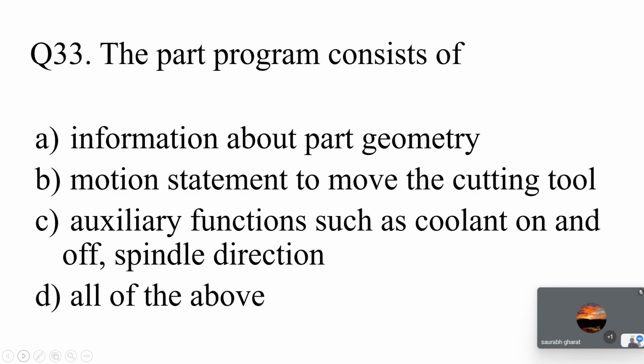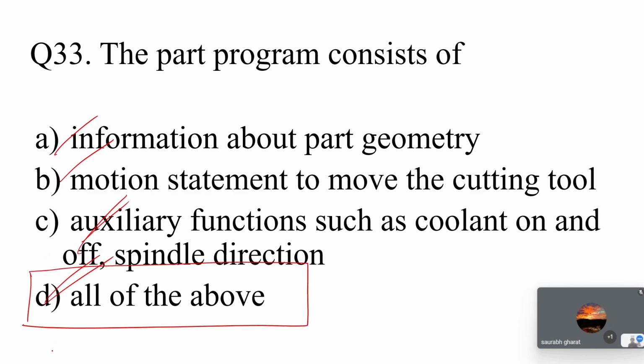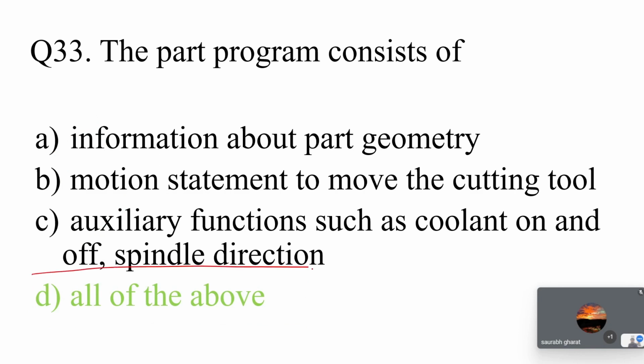So what does a part program consist of? Information about part geometry, yes, it is there. Motion statements to move the cutting tool, yes, it is there. And auxiliary functions such as coolant on and off. So all of this information is actually present in the part program. So all of the above is the correct option here.